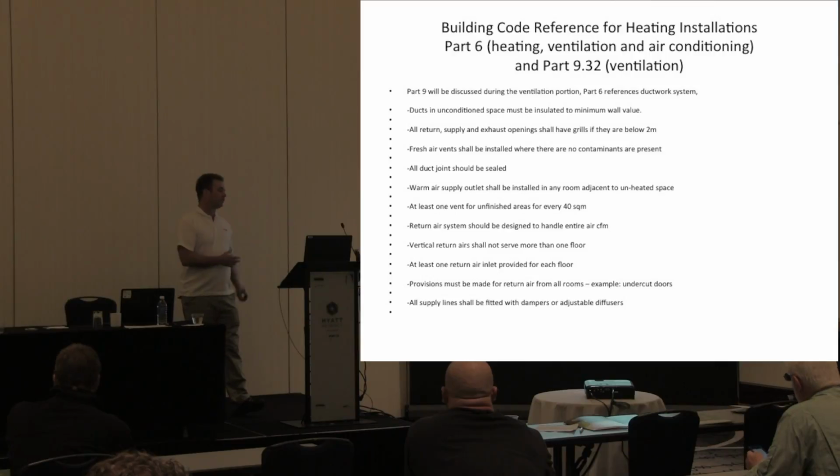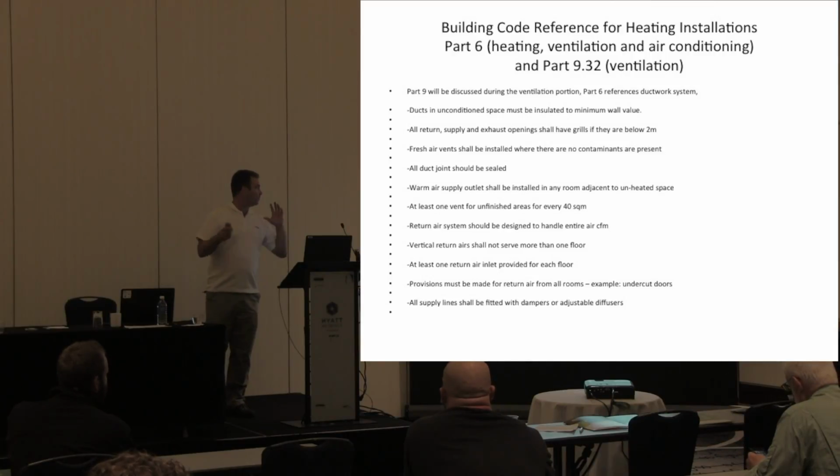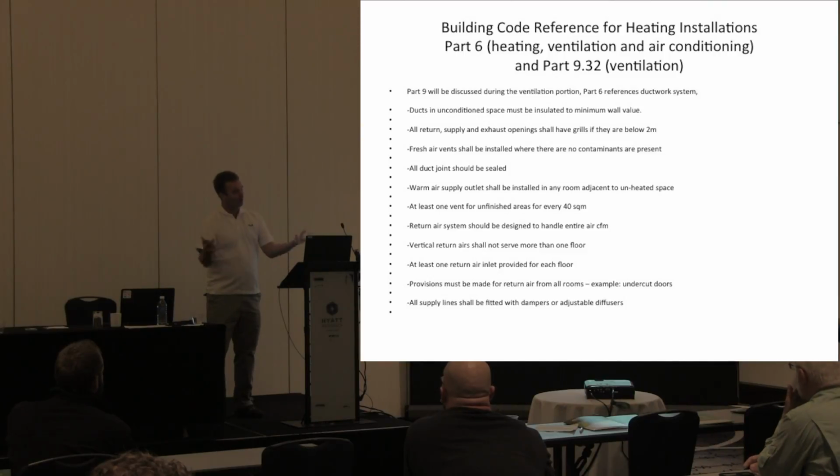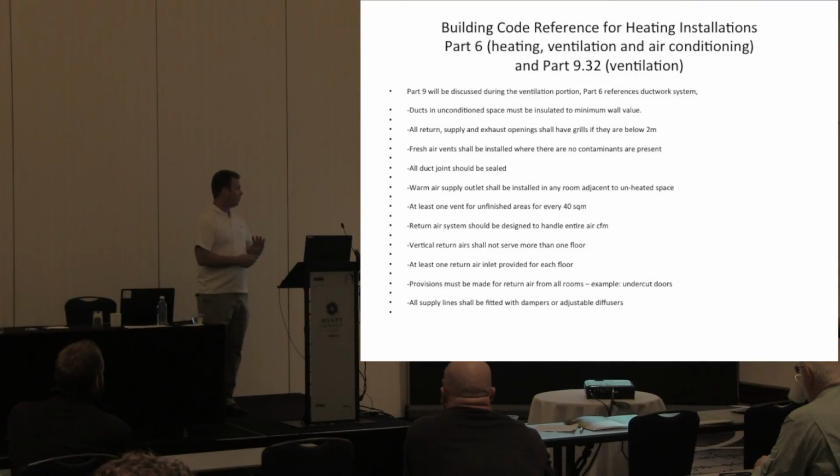The main reason why I put this in here for you guys is when you look at it and they run an 8x20 supply air duct to do the whole house, and then the return air duct is an 8x10 duct, there's a problem there. It's not going to get the same amount. Realistically, they should be close to the same size, or even bigger on the return side. So just when you guys are looking at things, most of the way I've set this stuff up is just so you guys are informed.